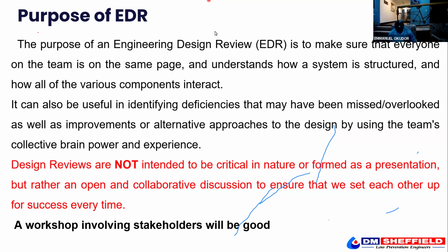So everybody must agree on the fact that the purpose for putting pressure vacuum relief valve is because, for example, we don't want to relieve any form of gas to the atmosphere. And if this is true, then it also means we need to have that documented in the basis for design. Then we start talking about the operations philosophy. So everybody must be on the same page.